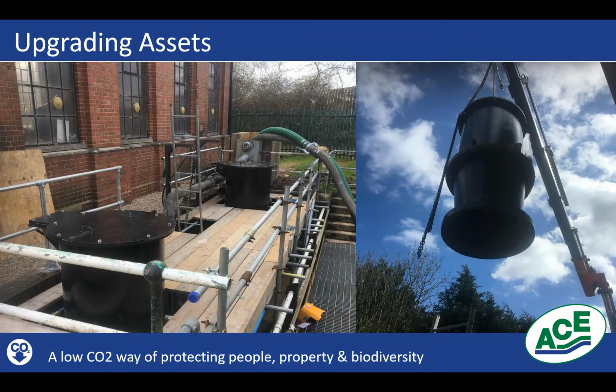So we upgraded the asset. The existing pumps were already removed. We then took out the pipe work to enable us to install some new canisters where we can put some new, highly efficient, fish-friendly pumps on the front of the pumping station. Now, as I mentioned before, the existing motors and gearbox and setup meant that the pumps could only operate at one speed. Now, the new pumps are being operated through variable speed.